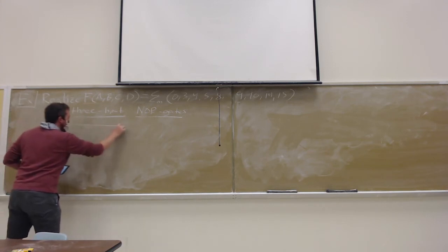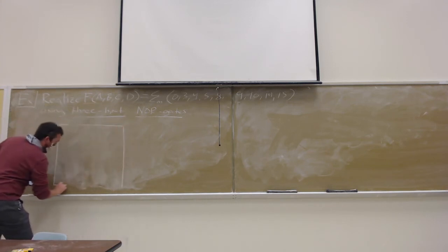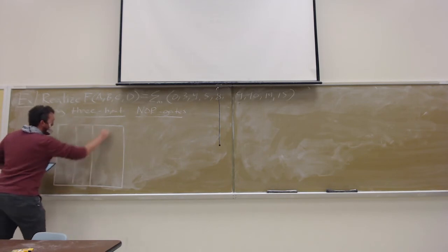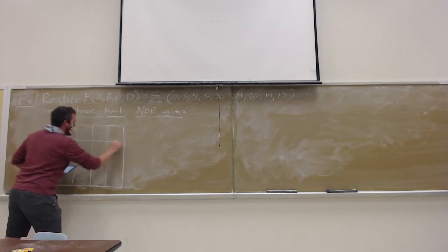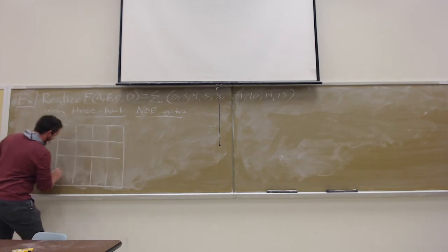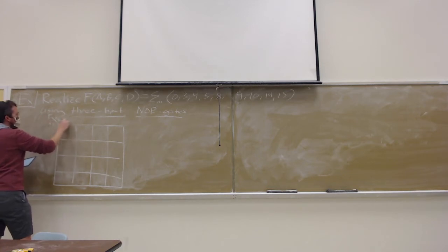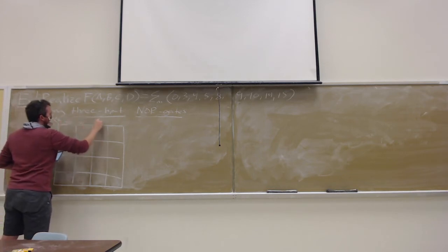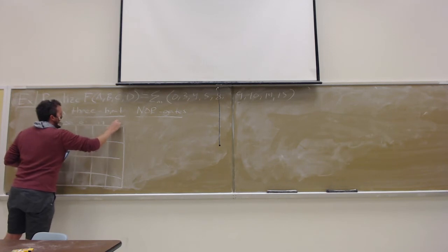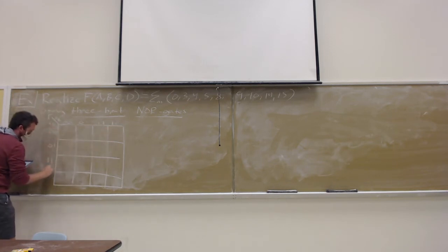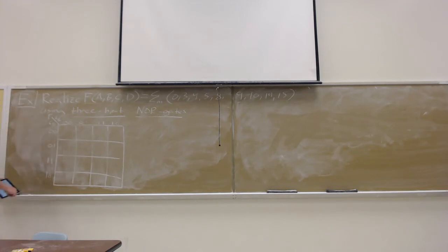So let's go ahead and set that up. We've got F, we've got A, B, C, and D, 0, 0, 0, 1, 1, 1, 1, 0, and 0, 0, 0, 1, 1, 1, 1, 0, and then we're going to drop in our values from our minterm expansion.